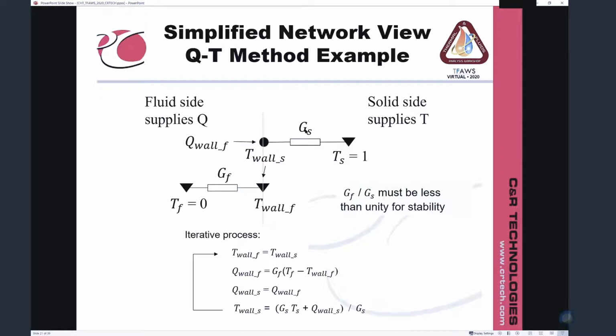Now suppose this was 1 watt per degree, and this was 2 watts per degree. Then we take the 1 watt here, we pull it out here, and now we get a delta T at 2 minus 2, so that goes to minus 1, which gives us a flux of positive 1. With that flux of positive 1, this goes up to 3, which gives us 2 watts into there, which gives us minus 5, and so on.